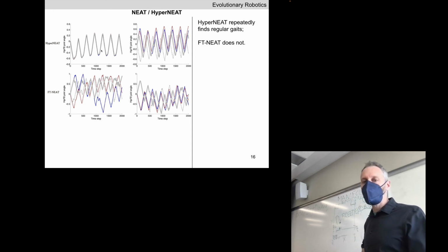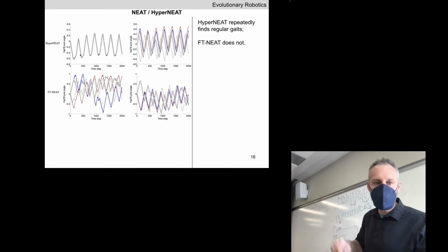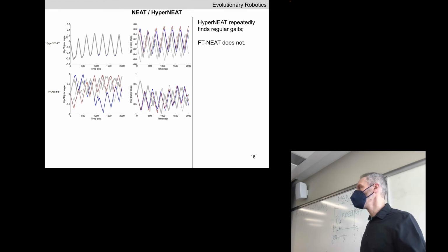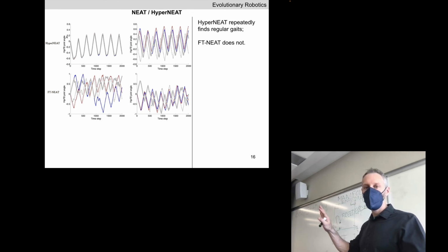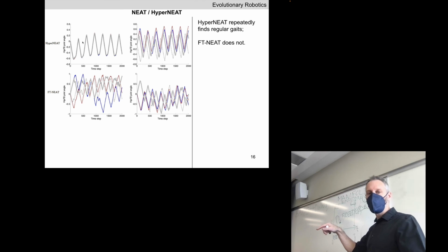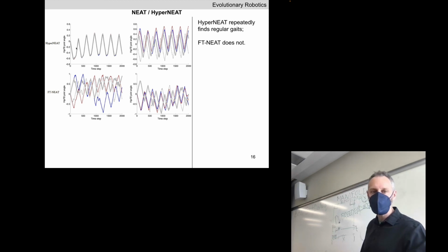Each individual curve corresponds to the hip forward and back joint angle. We've got four joints at the hip forward and backward, and we're plotting the angle of those four hip joints. And here's the result from our Pepe Le Pew, pronking. We can see that all of those four joints are moving in a perfectly regular pattern, almost perfect, not quite.